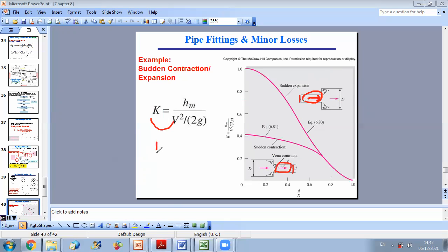So for the inlet, for example, they consider the characteristic velocity for the coefficient of loss to be the velocity after the inlet, because V is bigger than before: before, the area was very large and suddenly it became smaller. Whereas at the exit, if you have an exit to a reservoir, V becomes much lower, so I take V before. So always, in general, we take the highest V. In general it will be clear in the graph. But in case they don't give it to you, take the K relative to the highest velocity.